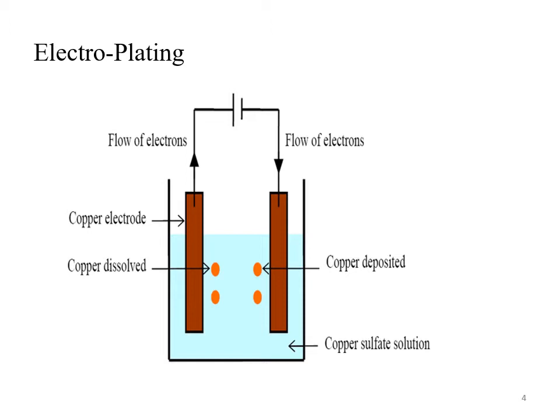Whether in ultrasonic machining or abrasive jet machining, the kinetic energy is transferred onto the abrasive particles, which gain the kinetic energy from one medium or another. In ultrasonic machining, it is from the energy of the ultrasonically reciprocating horn or tool holder. Whereas in abrasive jet machining, the abrasive particles gain kinetic energy by the conversion of pressure energy into kinetic energy, and then these high velocity abrasive particles hit the target surface,